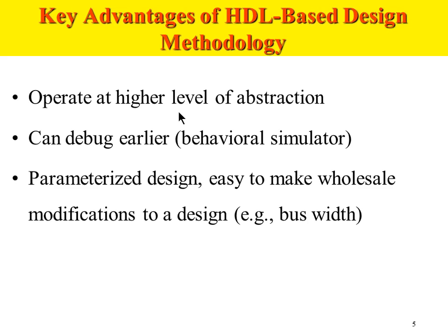When we work on HDL based design methodology, we work at Verilog HDL language based abstraction level. So we are not worried about gates and components at that time. We use the language and the language syntax to describe the design. So we are operating at one level of abstraction above the gate level, where we operate in schematics.